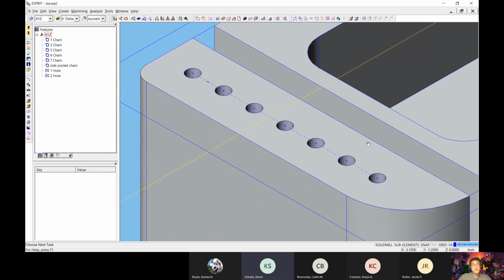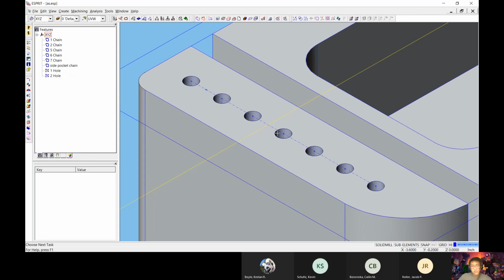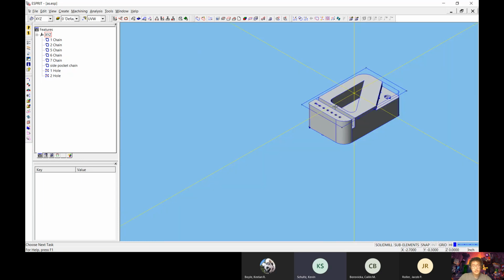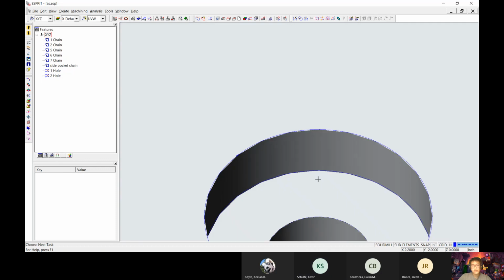Okay, I think I found the missing one. It was weird because they were all still selected. They all had gray on them, but there were only 6 loops there. But there were 7 gray spots, obviously. Can it show up as selected when it's not really selected? Yes. Sometimes it does that. But to confirm that you've selected all the holes, you'll see that there's a blue wireframe that encompasses the hole. And you'll see that there's 7 chains over here put into one. And then you look at this through hole with the counterbore, it will also have its own little chain.